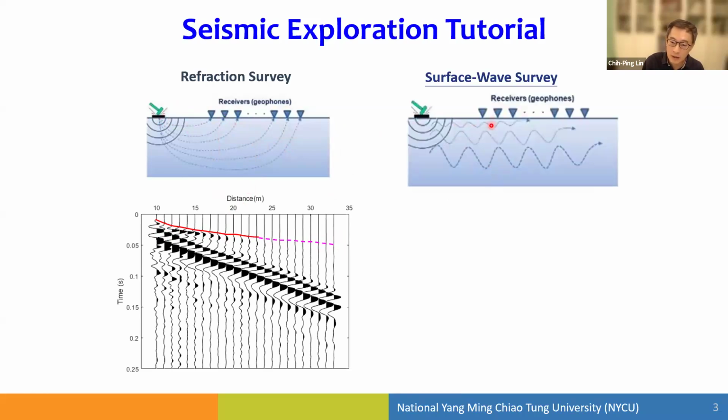Right, so the Rayleigh waves have different frequency components. High frequency travels at smaller wavelengths and has a shorter depth of influence, and longer wavelengths have a lower frequency and a deeper penetration. So the high energy you see on the seismogram is mainly the surface wave part, right?